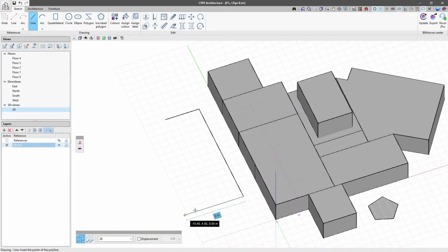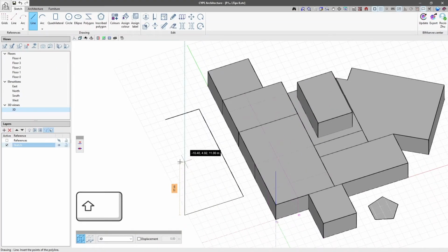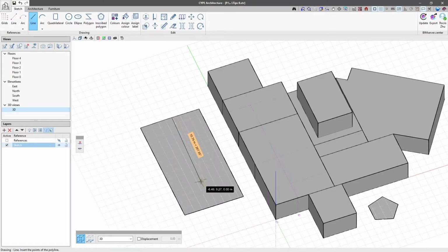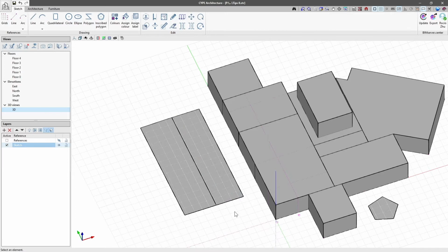If we click on the Shift key when drawing it, we will make the cursor move in the direction of the 3 coordinated axes. When a set of lines is closed, the program automatically generates the interior surface. We can divide any surface by entering a line that goes through it.